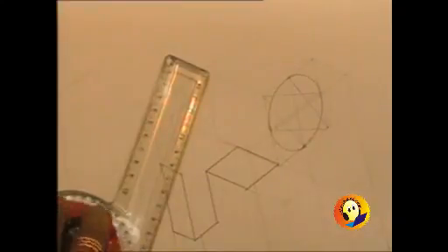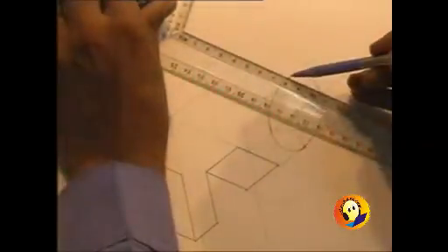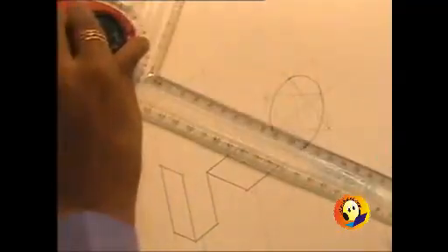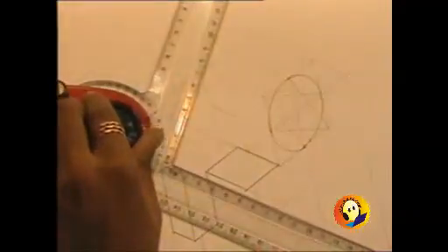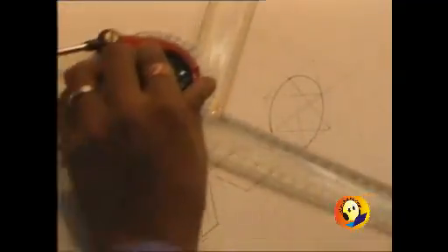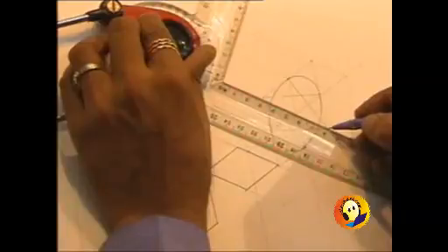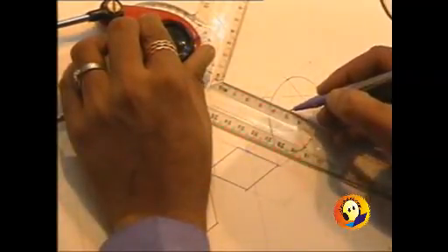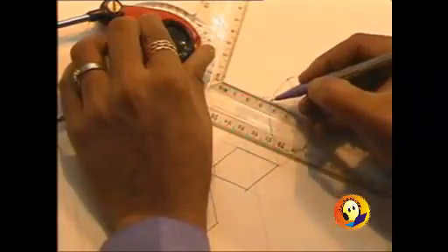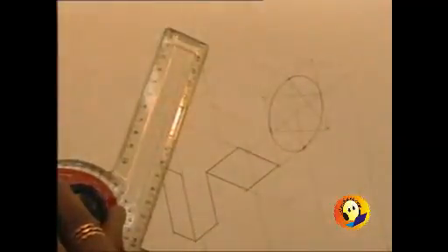Now this construction is very important. Shift the centers. You should be knowing what you want to draw, and only the corresponding center should be shifted. I am here just shifting the reference points. First of all, these lines are required, and then shift this center by a distance equal to, first of all, 30 millimeters, and then a total distance of 45. So I am marking these two centers here.